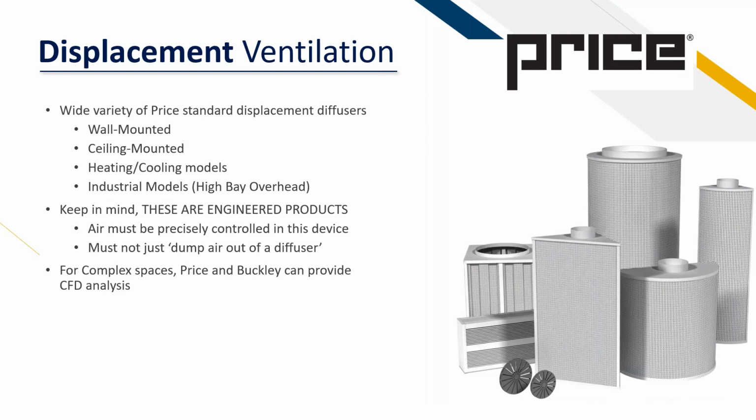With that said, we have a wide variety of displacement diffusers from Price Industries. That is who we use. We have the underfloor, we have sidewall, and we even have some overhead mounted options as well. These are engineered products, so we must make sure that we're designing these properly and precisely controlling the airflow coming into these devices. We don't want any just dumping out of this diffuser. We want to make sure we are engineering the whole application here. And then for some complex spaces, we can utilize Price's Predict team for CFD analysis to really help out on those complex spaces.